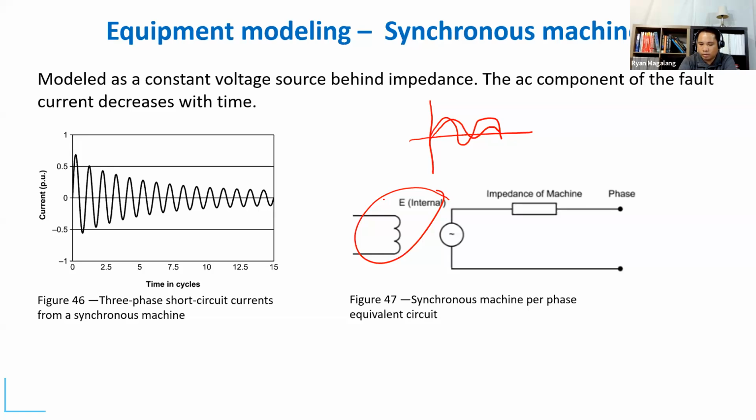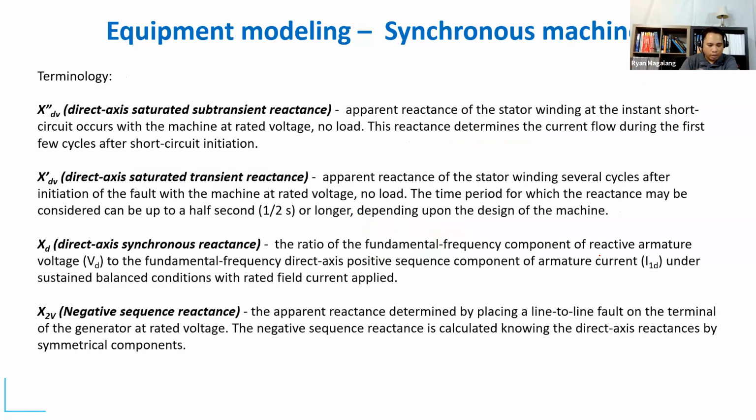On the other hand, since the synchronous motors have their own separate excitation device, the fault contribution would endure for a few more cycles. So that's the explanation for the main difference as far as fault contribution is concerned between induction and synchronous.